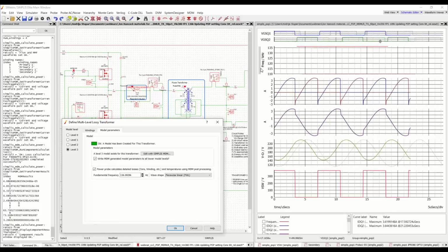Here in this schematic, we are actually measuring the frequency and it gets output here. So what would be the correct thing to do here is to run one sim with this checkbox disabled. Don't waste your time on running a possibly incorrect post-processing. Figure out what that frequency is, put it in here, then check the box, then click OK.